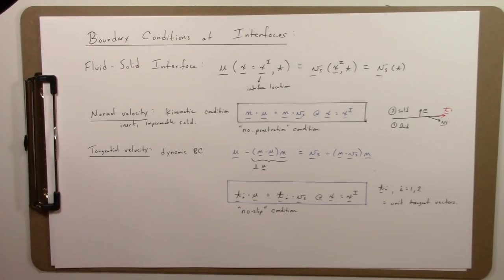Well, if we're considering inviscid or therefore irrotational flows in which viscous effects are neglected to a first approximation, and this approximation can be quite accurate for flows at large Reynolds numbers away from a solid boundary, the no-slip boundary condition may need to be abandoned at a first approximation. We then add a second approximation that will restore the no-slip condition and give us a uniformly valid approximation to the entire fluid flow field. We'll talk about this in more detail when we discuss boundary layer theory at the very end of this course.